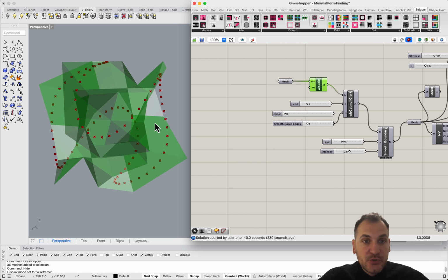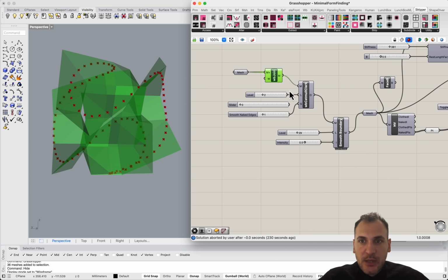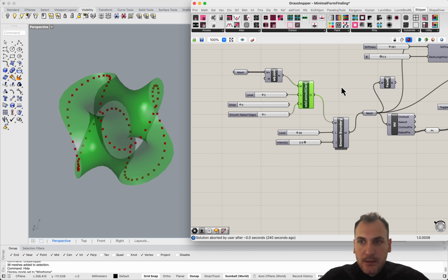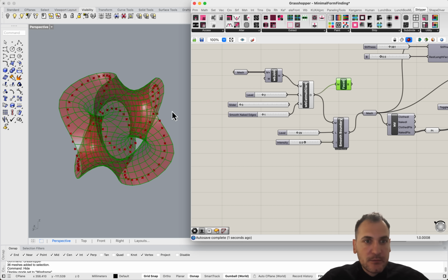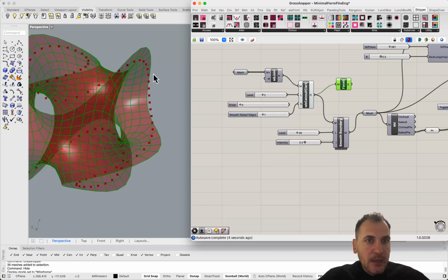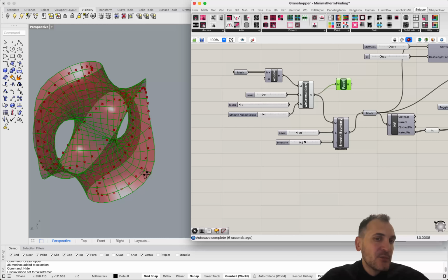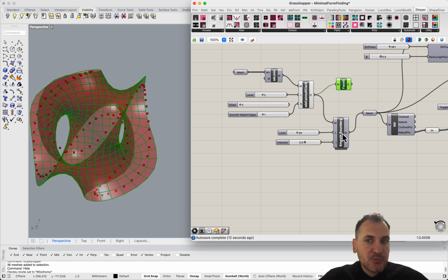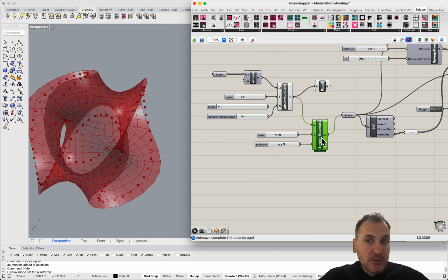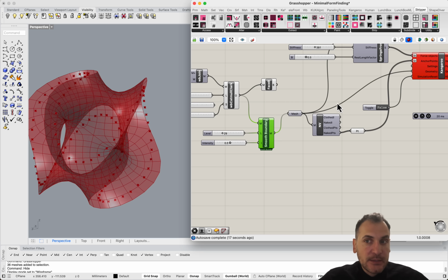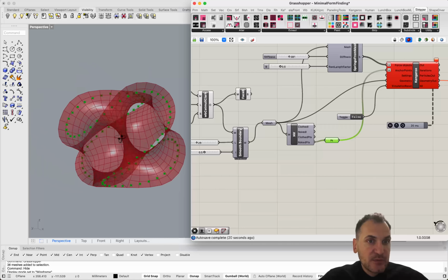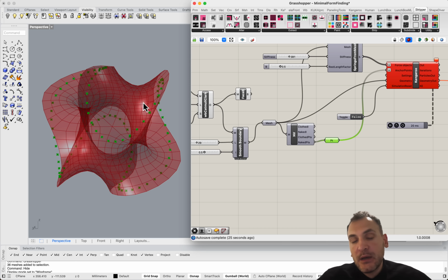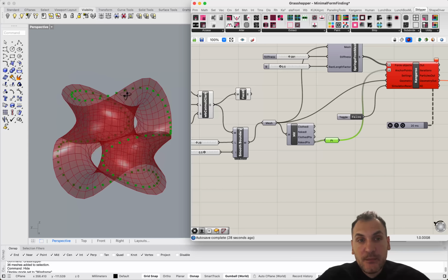And it first joins them, so we still have the same shape. Then we do the subdivision, and that gives us a surface like this. So you can see these are the faces. And this edge is kind of smooth, but we can actually make it smoother, right? So that's why we have this smooth boundary function. And you can also see these dotted lines, those are the naked points of the smoothed mesh. And you can see it's moving. It's being smoothed out, so it's displaced.